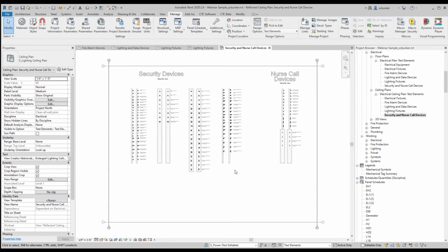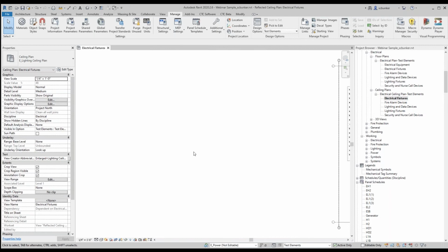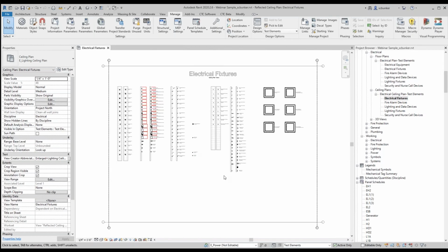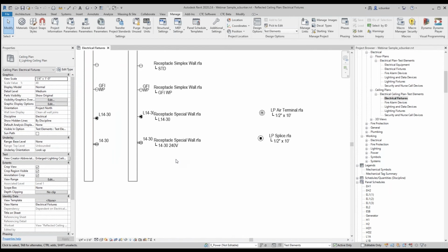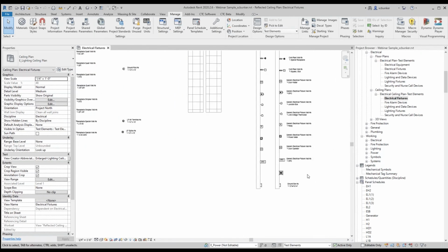Stephen, there were a couple of questions that came in that relate directly to what you're talking about right now, and I think this is a good chance to throw that out there. Across the electrical, fire alarm, lighting, security, nurse call, all of that, those are all using that generic symbol methodology, correct? Where appropriate, yeah. And additionally, every one of them per their category, again where appropriate, is using the proper electrical connector in that category, right? Yes, they are. They are actually a three-dimensional, quote-unquote, family that is using the symbolic representation that also has the power connector and some graphics to go along with it.